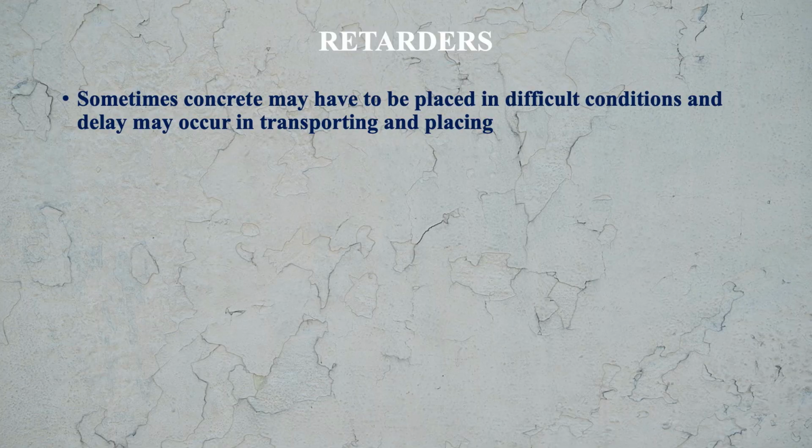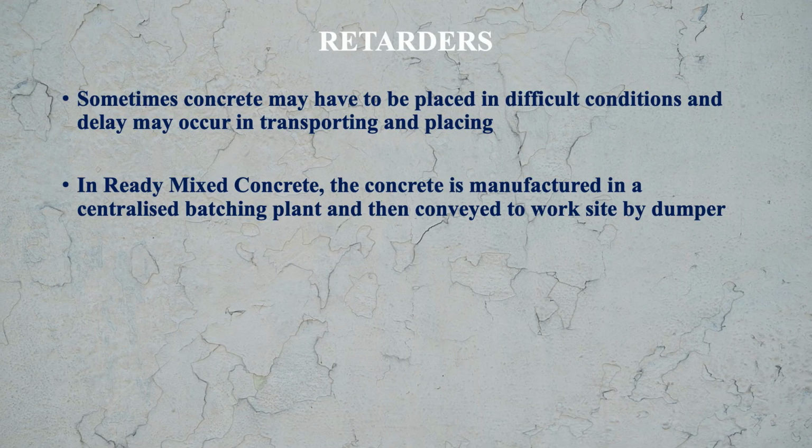Sometimes concrete may have to be placed in difficult situations and delay may occur in transporting and placing of the concrete. So these retarders take care of that additional time required for transporting and placing of the concrete. In ready mix concrete, the concrete is manufactured in a centralized batching plant and conveyed to the work site by the dumper. So during that transportation process, transit time, that concrete should be in a workable state and these retarders ensure this situation.